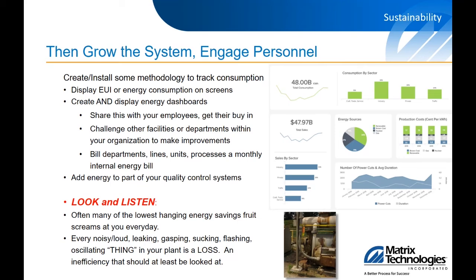They had I think 4 of those vacuum pumps. They were 75 horsepower or 100 horsepower, that size range, so pretty good load. And they had been leaking for so long and so much water that the footings on the motors, or the concrete, was getting eaten away by the cooling water for the vacuum pump. But that didn't happen yesterday. That is a years-long inefficiency running that should be fixed.